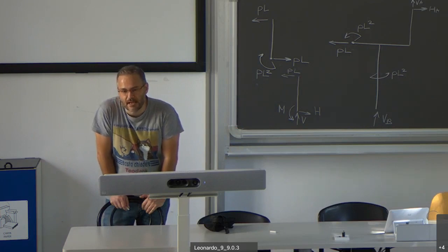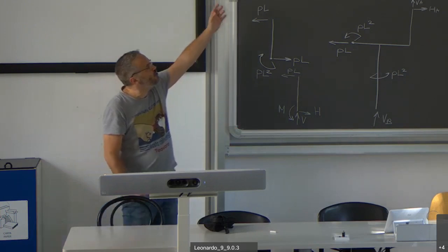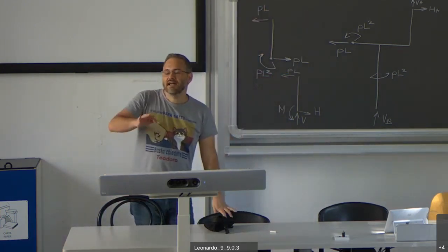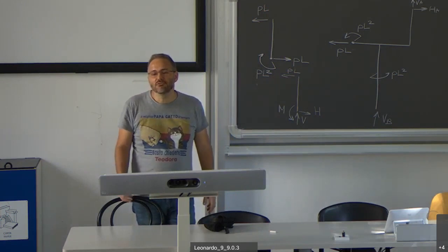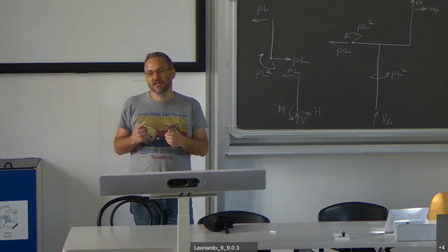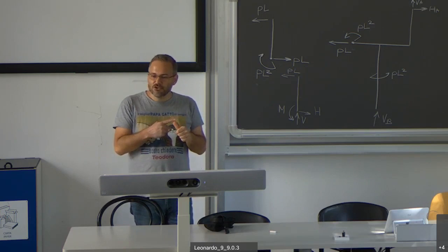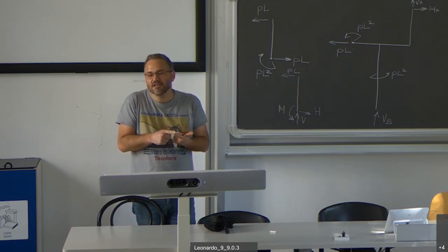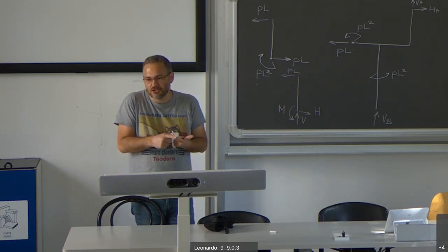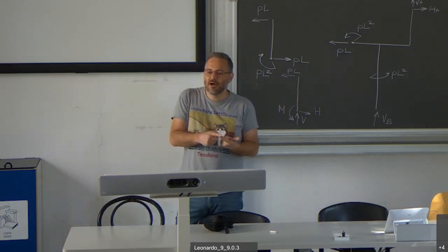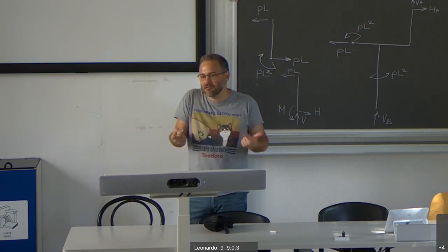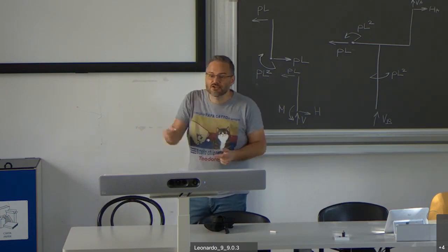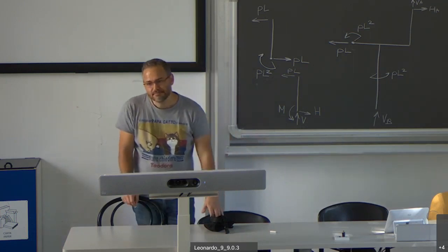When you have unknown forces, unknown means unknown, in magnitude and direction. So you're not supposed to know the direction a priori. You fix an arbitrary direction, and you get the actual one by looking at the sign. As for the magnitude, it is a number, so basically it's calculations, you have to get it right, okay?